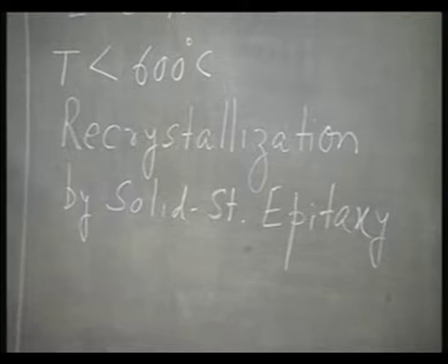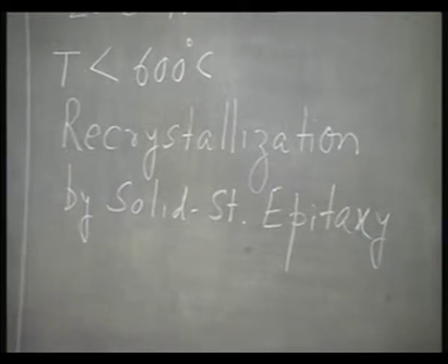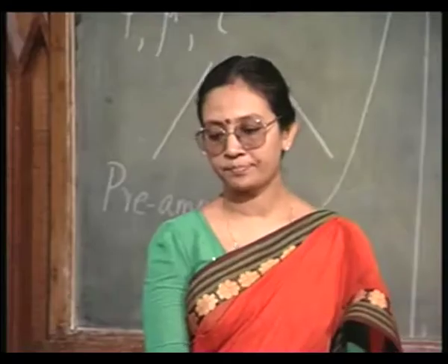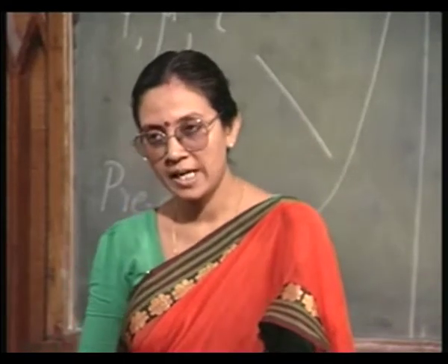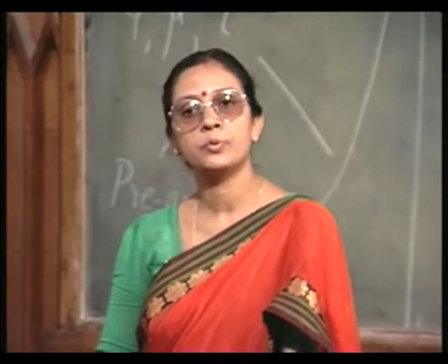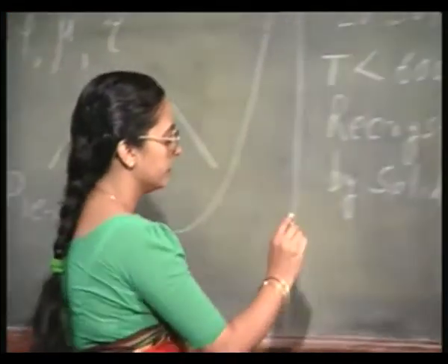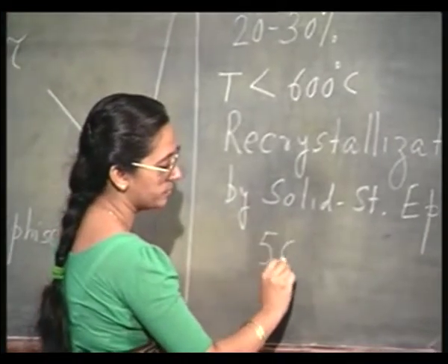So, what you have in this temperature range is recrystallization by solid state epitaxy, and carrier activation can be up to 90%, 50 to 90%.